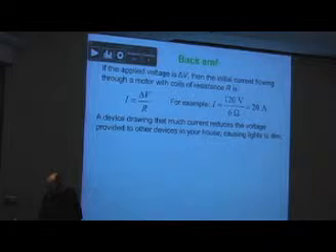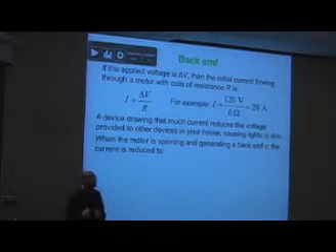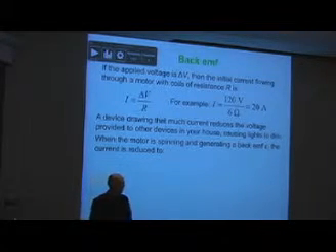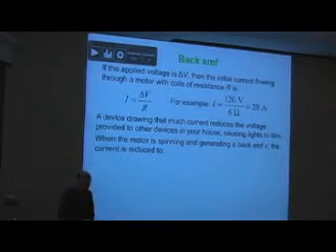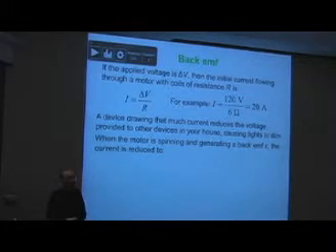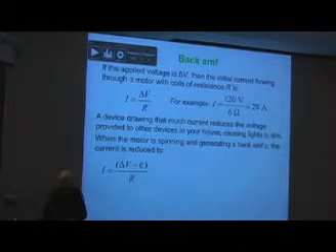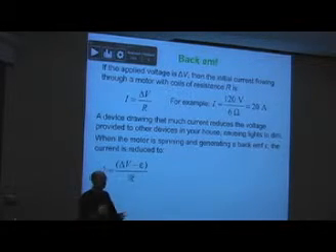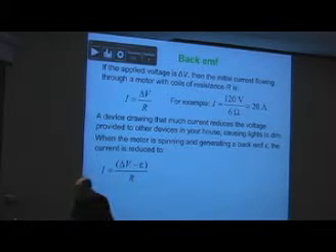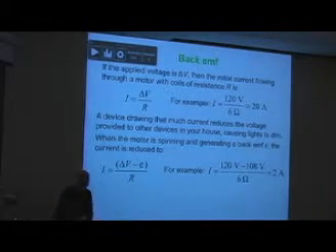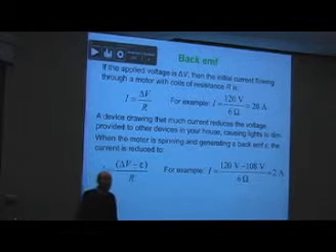And then, let's say that when the motor's up to operating speed, it doesn't take too long to get there, a couple of seconds, we generate 108 volts of back EMF. So then it's like a 120 volt battery hooked one way, and a 108 volt battery hooked in the opposite direction. We have a net of just 12 volts there. And so our current is 2 amps.